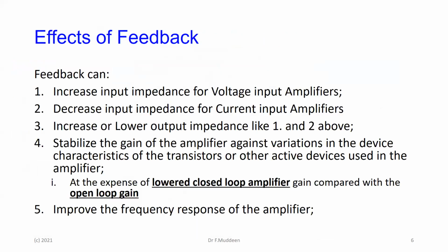So these were just some circuit things. Forget that for the time being. What this part of the lecture did was to show, for the various types of amplifiers, leading to the exam question, what are some of the things that feedback does? Remember, for voltage amplifiers, we wanted the input impedance to be as high as possible.